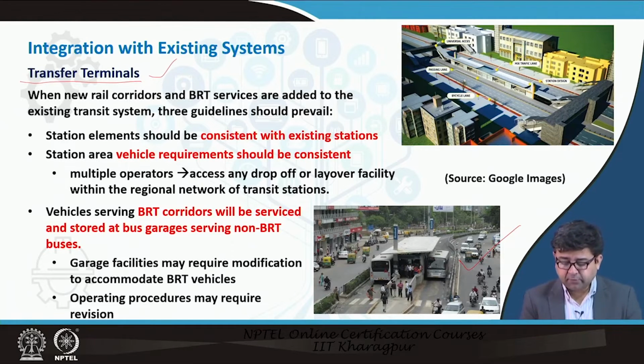You have to have good facilities for the pedestrians to cross once they get on or get off the bus, right. Otherwise, since this is a median type of BRT, nobody would be able to access this station from the footpath on the sides of the road. So, in order to access this, you need good connections, you need a zebra crossing to cross.